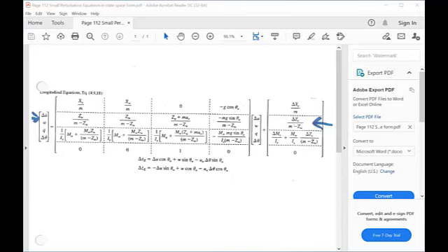And it is complicated. I mean, the trim solution was complicated enough. And the fundamentals are that you definitely want to make sure you can trim the airplane before you get off the ground, right? Otherwise, you're going to die for sure. You want to be able to trim at all airspeeds. So we start with that. That's fundamental. You want to be able to do the equilibrium condition at all flight conditions. But now we want to know, how does the airplane behave when the pilot perturbs something? Or we hit a gust and we get an alpha perturbation. And that's important as well.